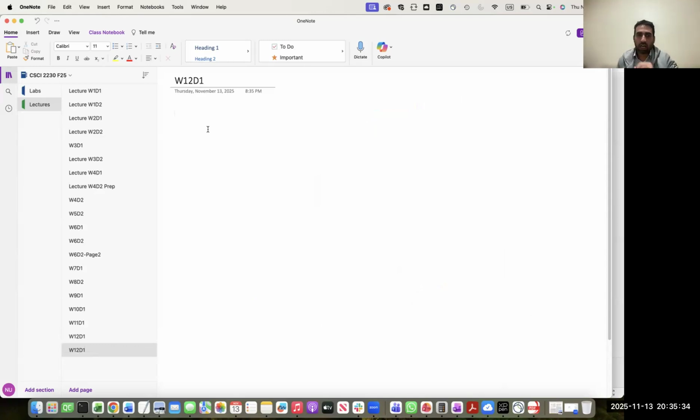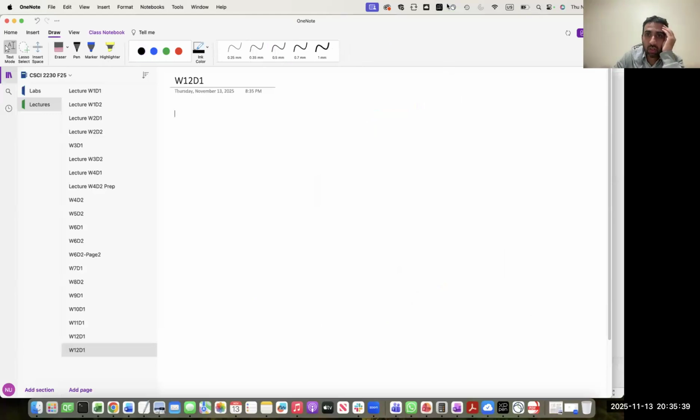So I was giving you an example of polling in the context of timers, and we have seen those examples multiple times in our previous lecture slides. Suppose this is your TIFR0 register, and this is the bit at the 0th index, which is basically the overflow flag for timer 0.